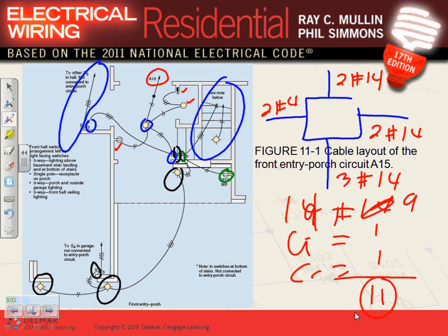But clamps, they have no clamps. I don't think they count these as the clamps internally. So if you get the clamps out, no clamps, you're there with a box like this, 10, right? Because we're short. There's nothing, no studs, nothing coming out of it. Very good point, Chris. You're thinking box fill calculation. Any question, guys, about this circuit? Any question about this circuit?